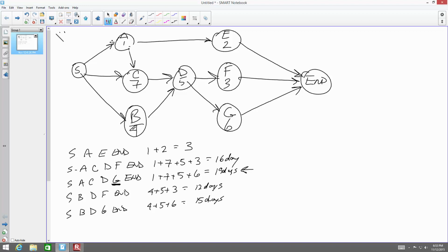Time is of the essence. You see that in every contract that exists. I don't know if I've ever seen one that doesn't exist. And you have that in there so that if there is a delay, you can get compensated for it. So it would be answer C there. Damages for delay cannot be claimed if time is of the essence is not in the contract. So you want it in there so you can get your reimbursements for damages due to delays. Delays not caused by you, of course, but it's a very, very important part of the contract.